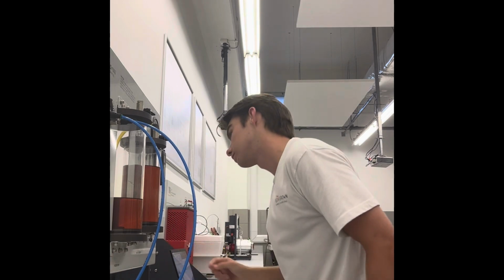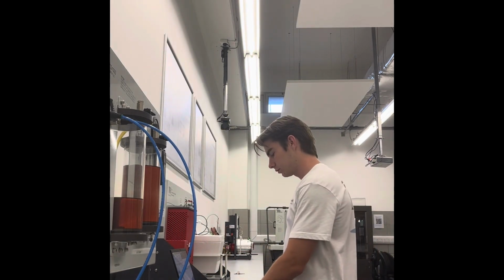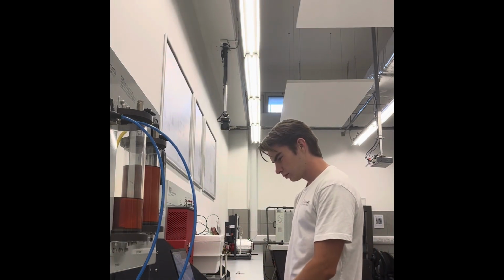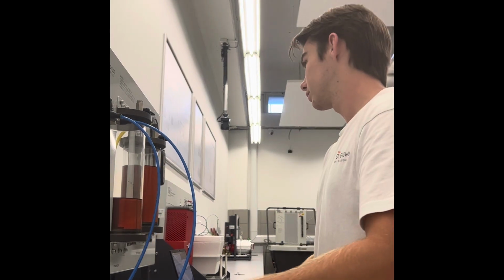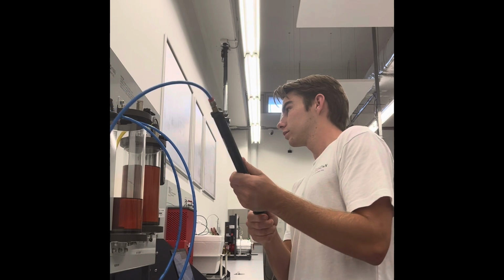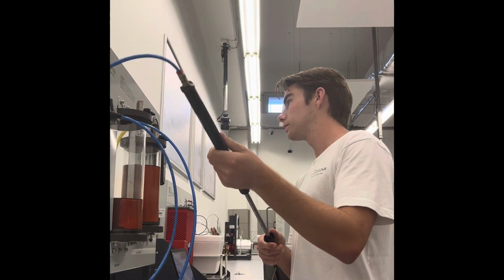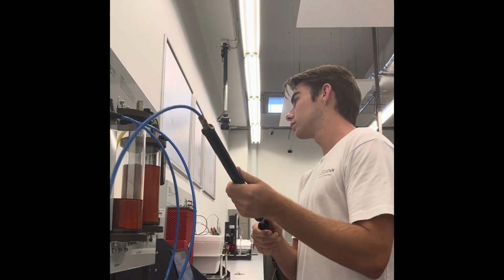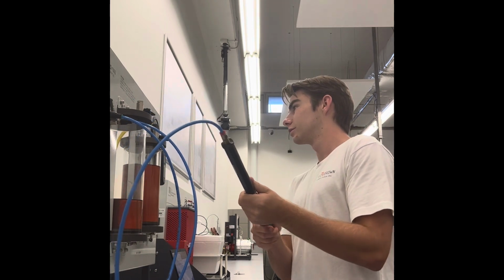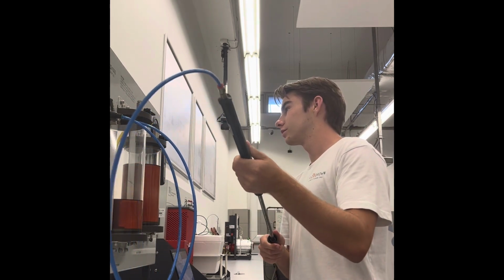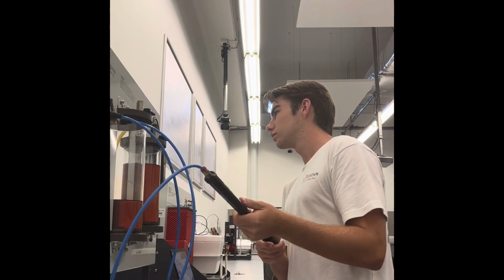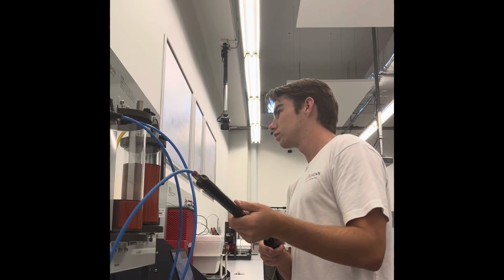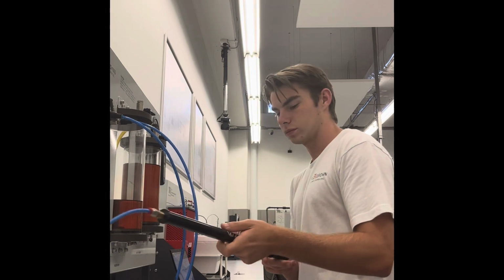So here is me actually running experiments using the Boyle's Law apparatus. Right now I'm entering some data in the computer, but as you'll see here, this is me increasing the pressure level over in the reservoir cylinder. By pumping that up, the pressure is being increased, and you can see the fluid levels in the test cylinder actually rising, decreasing the volume, showing that inversely proportional property that Boyle's Law shows.